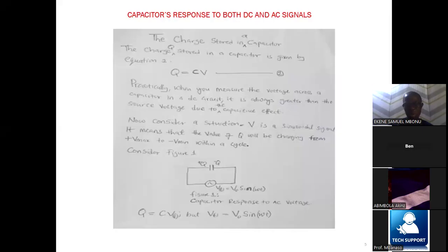The rated voltage of a capacitor should be a bit above the rated voltage of your source. Otherwise, if you have a 12 volts supply, same bridge rectifier that is reading 12 volts, the moment you put a capacitor there, it's likely to get to 17, 18 volts.